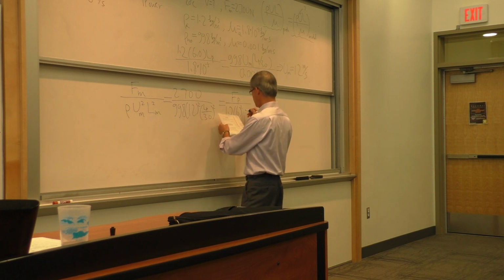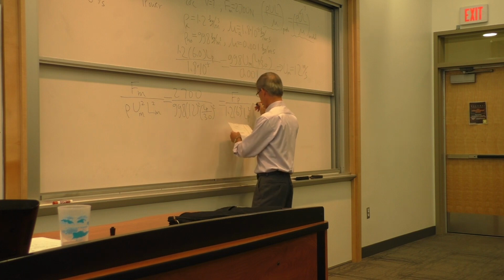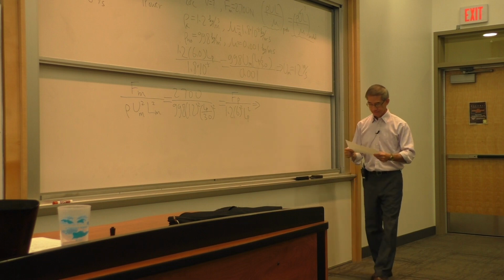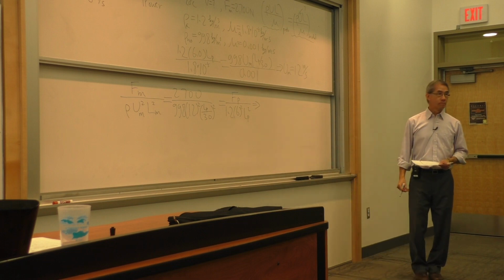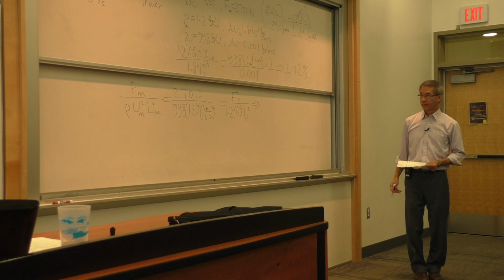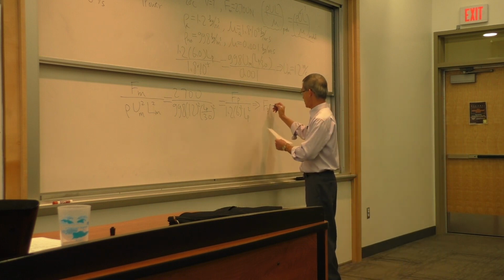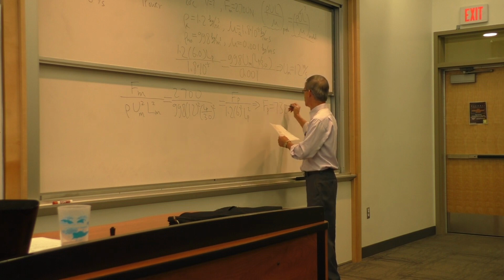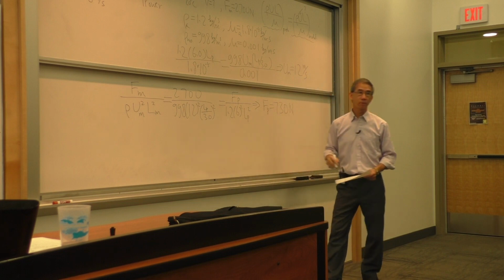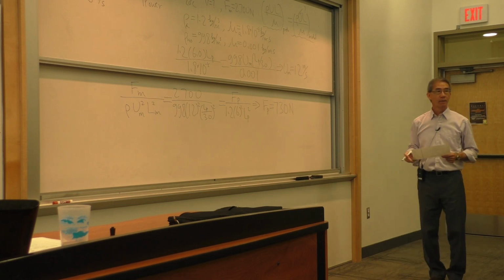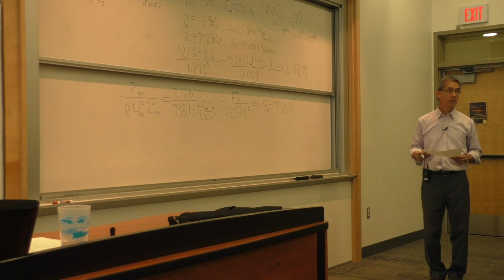So in order to get the drag force, I just equate the two drag coefficients. And knowing the length scale is 1/30, this resulted in that, in air, for that 30 times bigger model, it's about 730 Newton. And I now have the matching condition between my water test and my actual application in air.